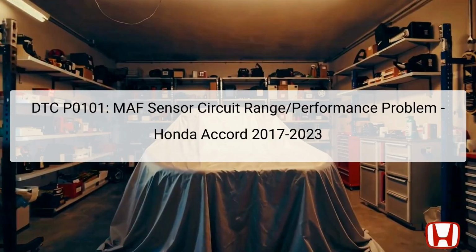The diagnostic trouble code, DTC P0101, indicates a performance problem within the mass airflow, MAF, sensor circuit. The MAF sensor is a crucial component in the vehicle's engine management system as it controls the amount of air intake into the engine. This ensures the optimal air-fuel mixture for efficient combustion.